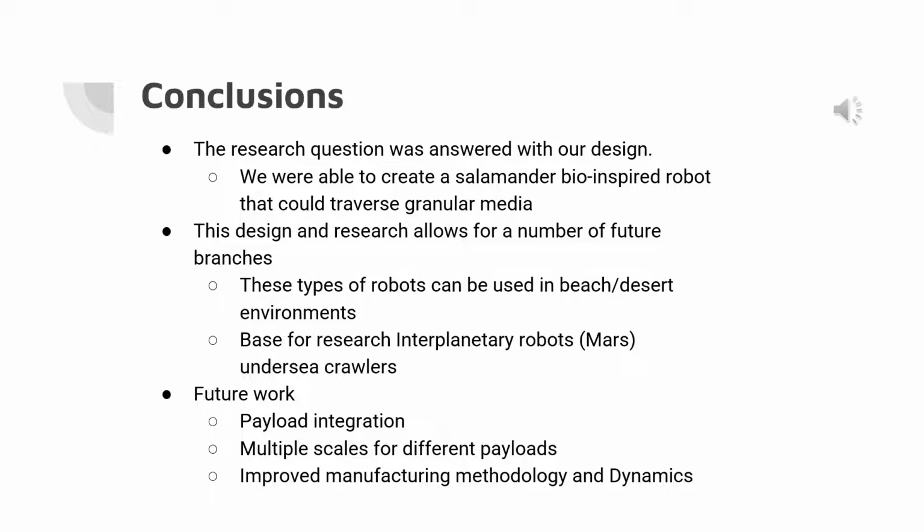As you start to put these materials and these payloads inside of the robot, then you start changing the mass and the inertias of the different parts. As you do this, you need to start looking at the different dynamics that this creates to make sure that the robot continues to operate the way that you want it to.